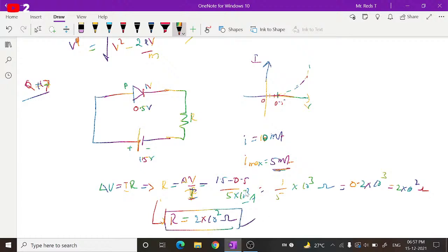Okay. The question is given in a little confusing way, so you have to understand how to deal with this kind of question. In a PN junction diode when forward biased, it has a drop. This is nothing but the drop in potential. Whatever potential we give will not be used for conduction. That means only after overcoming this, conduction will take place. That is the meaning of it.